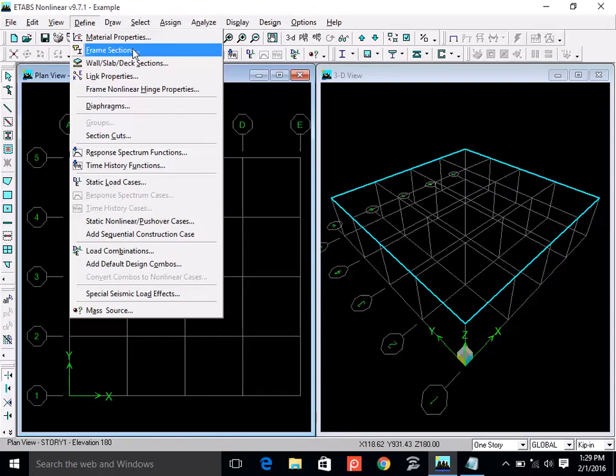Now the question is that at the beginning, when you are designing the structure, you are not sure about the sizes of beams and columns, which means that you need to do some approximation, or use some guidelines which tell you some tentative sizes. Most of the time, the sizes we begin with are based on deflection criteria.